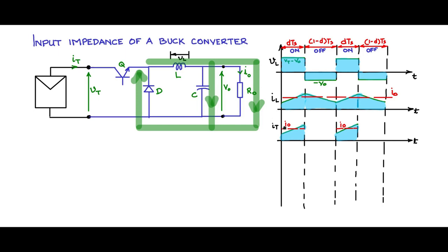Observe that the terminal current is not continuous, it is switched, broken up. When IT is flowing, the power is some finite value. When IT is 0, the power drawn from the panel is 0, which means you are underutilizing the panel. For the panel to be delivering peak power, we need IT to flow continuously. So what is the continuous equivalent of IT here?